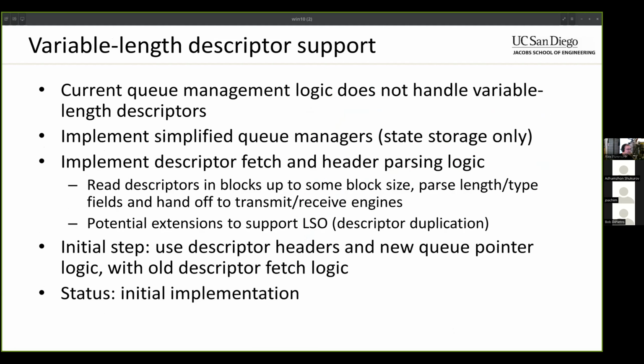Let's see. And then the next thing I'm going to take a crack at is the variable length descriptor support. Once I have the shims fully squared away, this will be next up, because this one is hopefully going to improve the timing on the Intel devices. That's one thing I've been doing actually. In addition, a bunch of timing closure work and timing optimization work on the Ethernet MAC and the PTP CDC components to get things working at 25 gigabits per second on the Stratix 10 MX.